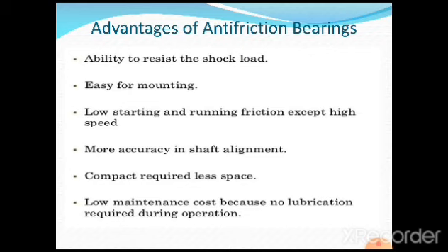That load will directly come on the spindle and in turn to the bearings. If the bearings are not designed with the proper type of material and not properly mounted, then all these problems will exist. There will be vibration in the machining operation also. But apart from that, these bearings have the capacity to absorb shock loads, that is, sudden loads. As per the machining operation, the cutting force will go on changing continuously. Sometimes it is very low, sometimes it is very high.